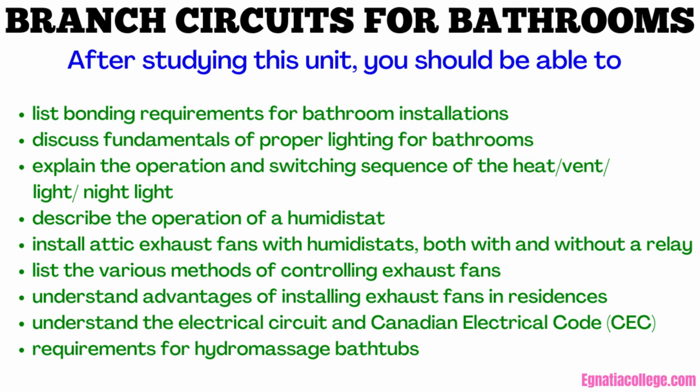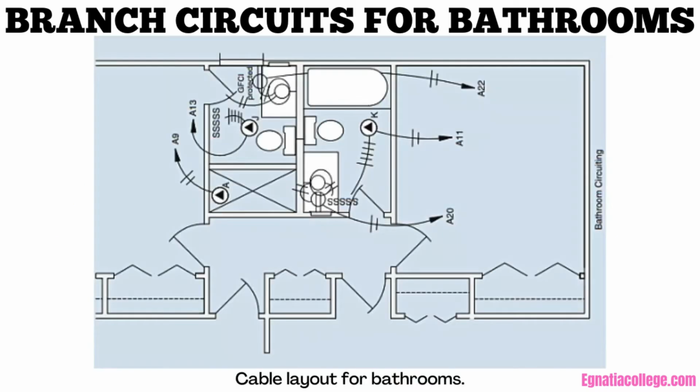Understand the electrical circuit and Canadian Electrical Code (CEC) requirements for hydromassage bathtubs. Electrical equipment in bathrooms and washrooms requires special installation considerations. For example, in the residence used as an example in this textbook, the hydromassage bathtub in the inside bathroom requires ground fault circuit protection, Rule 68-302. Switches must be properly located.